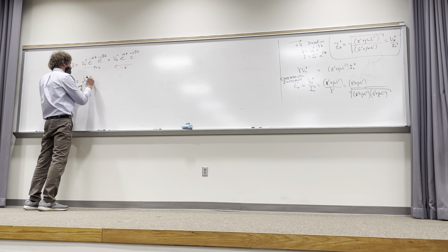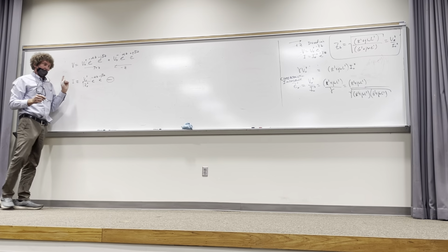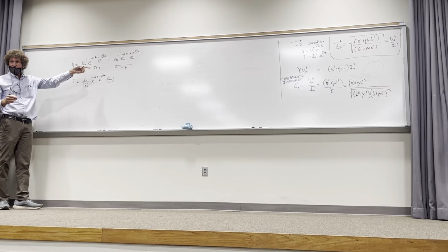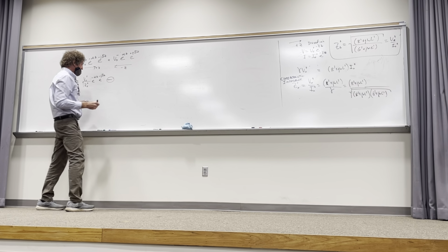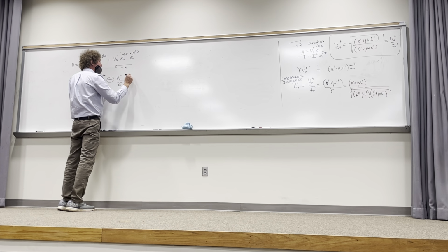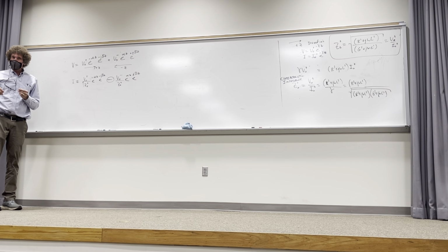And then it would be e to the minus alpha z, e to the minus j beta z, and then here there'll be a minus sign, because I told you the ratio of V0 plus to I0 plus was minus Z naught. Do y'all remember that? So then it will be minus right here, and it will be V0 minus over Z0 plus, and then it will be e to the alpha z, e to the j beta z. Now just remember that. Now I got one more thing and then we'll do the problems. Y'all with me?